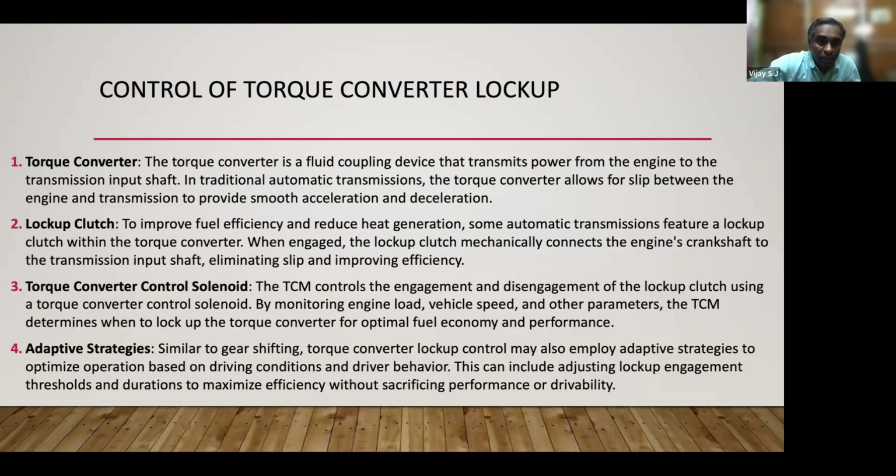And the torque converter is a fluid coupling. It's basically a fluid coupling. I don't know whether you remember city clutch introduced by some of the scooters. City clutch. So in city clutch, the torque converter technique only they use. They use a fluid coupling to transmit power from the engine to the output shaft or the transmission shaft. So that is what it is doing.